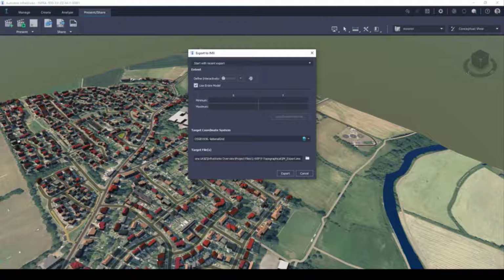I'd recommend using the same coordinate system throughout a project as good practice, and to model everything geospatially correct, no matter the application used. This will mitigate against any coordination issues that may arise as the project progresses.